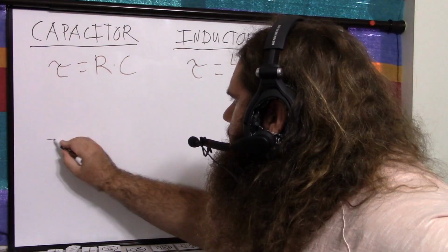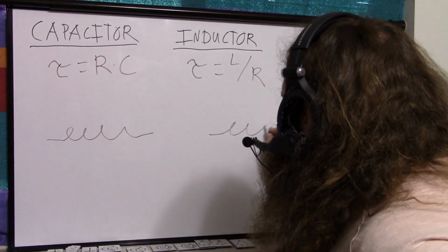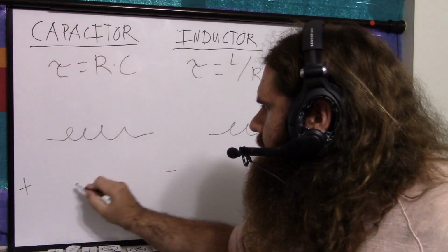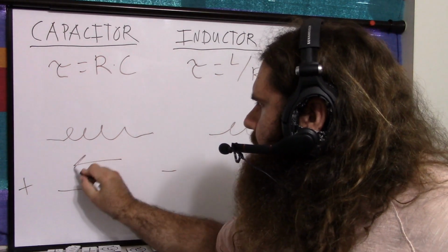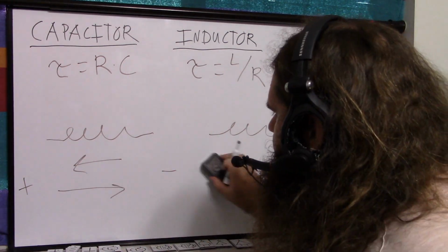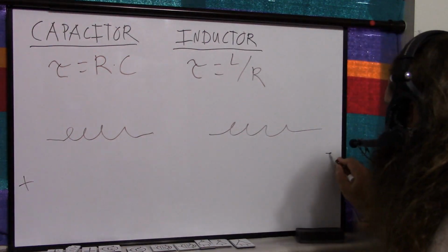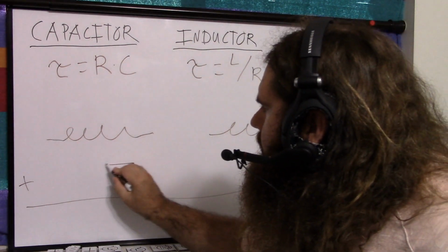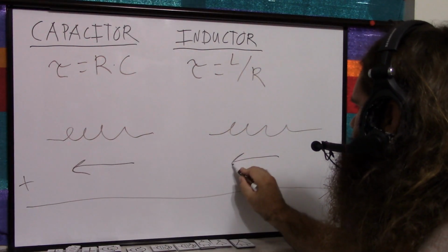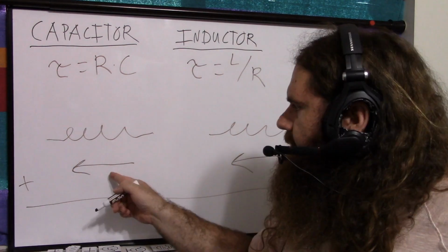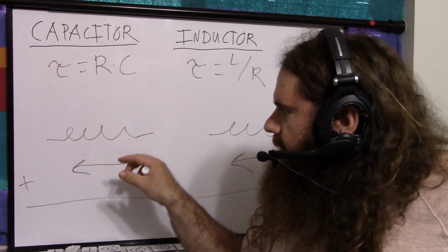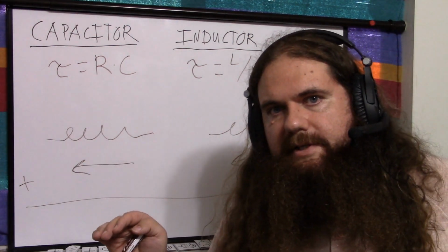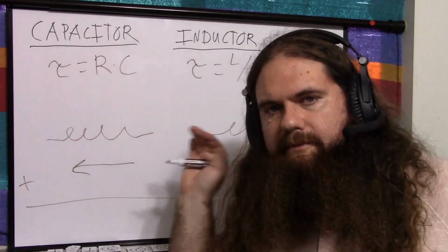What about an inductor? Let's say you have an inductor and another inductor. So you put a certain voltage across this inductor and you're trying to charge it up, and there's going to be an EMF from the battery and a back EMF from the charging process. Well, instead of that, let's say you have the voltage across both of them. So you've got your EMF way across here, and they're each going to try and put a back EMF like this. So it's kind of like batteries in series. This is generating a back EMF, which is kind of like having a little battery pointed the other way, and so is this. So the batteries are kind of in series, and so the back EMF back voltages are adding together.